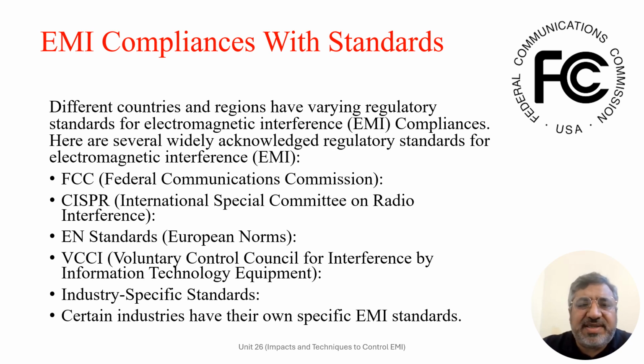CISPR standards provide guidelines for the measurement and limits of conducted and radiated emissions from electronic and electrical equipment used in wireless and non-wireless communication. Common CISPR standards include CISPR 22 for information technology equipment and CISPR 25 for automotive electronics.